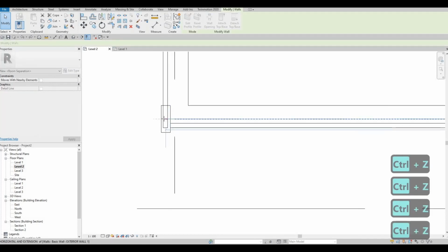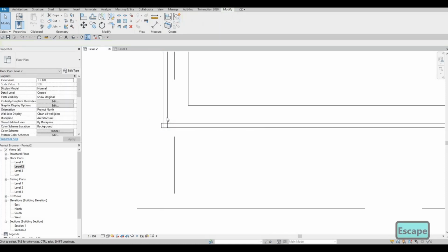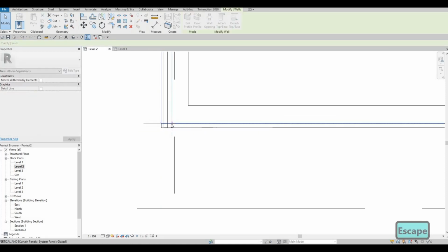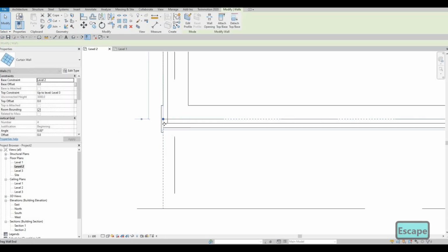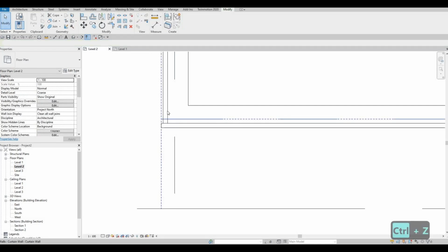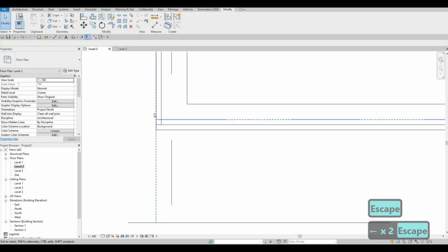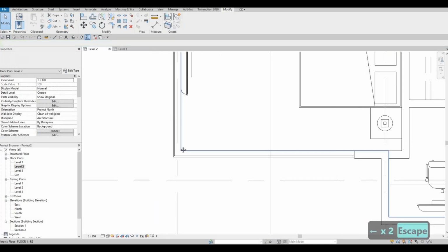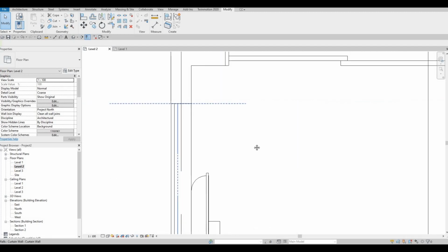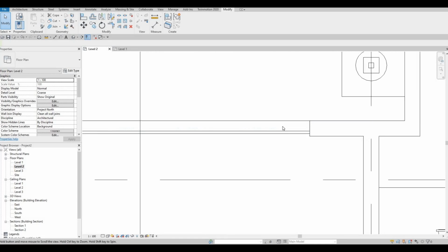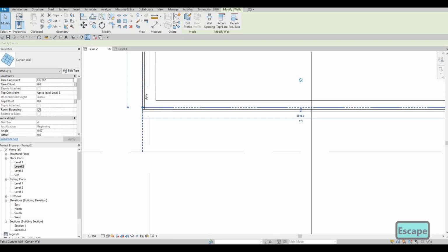So now we could just extend this to the point that the wall disappears and only curtain walls remain. And then here we could just adjust so that it's cornered like that, 90 degrees. So that means it will be at the edge like that. So that will be fine. I'm happy with this.